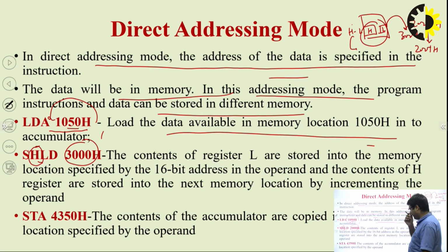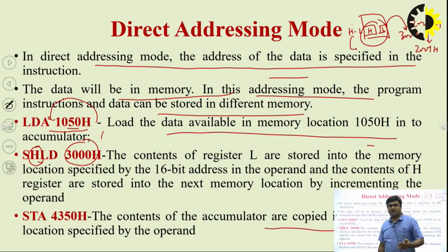Similarly, we have STA 4350H, store accumulator. The content of the accumulator is copied into the memory location. So in store operations, we are moving the contents from the accumulator into the memory location. This is the memory location.